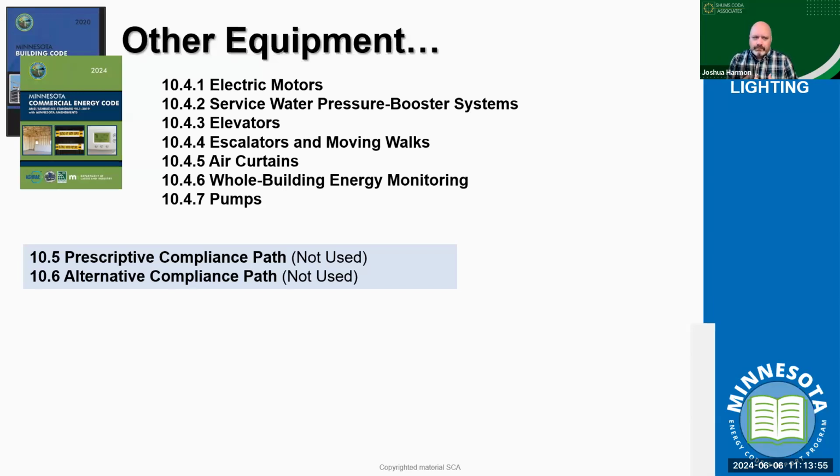I've used the example before where we're talking about equipment longevity as much as energy conservation. A project I know of was more of a theater application, and they had a variety of lights that were supposed to have some controls installed. The appropriate controls were never installed, and so the lights had never turned off. After almost 10 years of being on, they started to experience mass failures in their lighting system. So they called the county, they called the building department, because they thought they were having some kind of wiring issue. We've got some kind of short somewhere. Can you come help us?